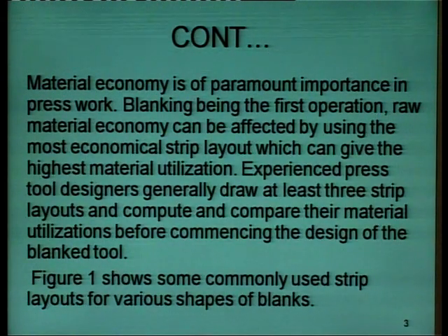Now, material economy is the most important point in press work, that is the cost of the material. Blanking being the first operation, raw material economy is affected by using the most economical strip layout, which can give the highest material utilization. We have to choose that strip layout which gives the maximum material utilization, because if utilization is maximum, obviously losses will be less, the cost will be low, and ultimately profits will be high.